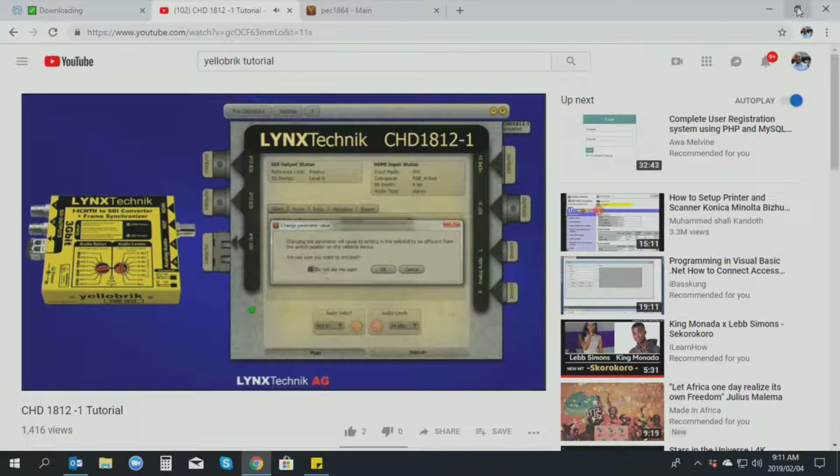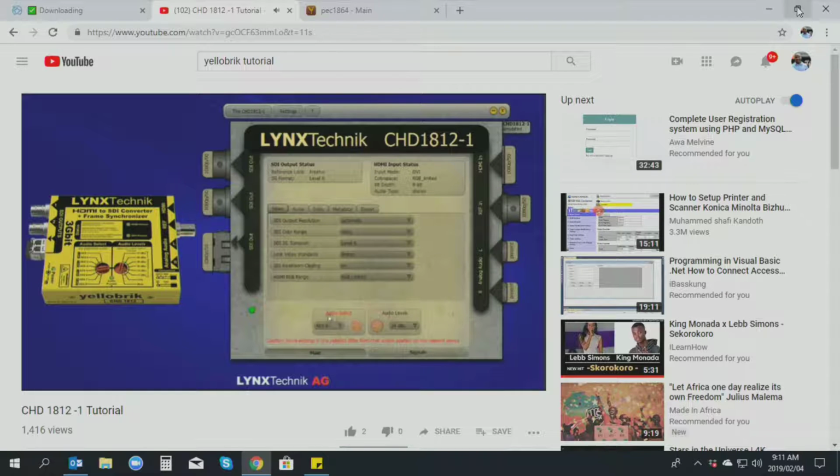So there's a conflict, and you can turn this little dialog off because it gets a bit annoying after a while. You can see now it's actually gone red, and it's telling me that there's a conflict, not a problem. And actually, this LED, the power LED, when this situation arises, it goes red, and that tells you there's a difference between the physical switches and what's been set in software. So you know, if you haven't got the software connected, and there's something weird going on, or there's a change between this and that. And this is what this is: enable local parameters.